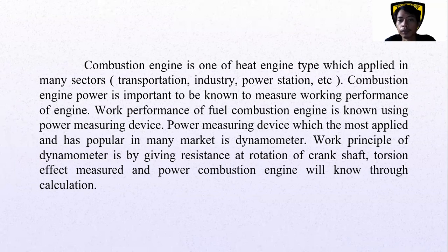Work performance of a fuel combustion engine is known using a power measuring device. The power measuring device which is most applied and popular in the market is the dynamometer. The work principle of a dynamometer is by giving resistance to the rotation of the crankshaft. The torsion effect, measure, and power of the combustion engine will be known through calculation.